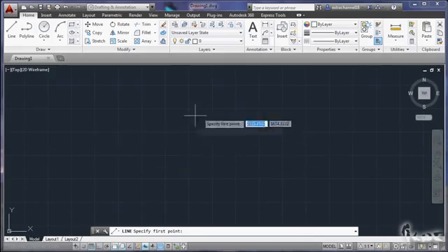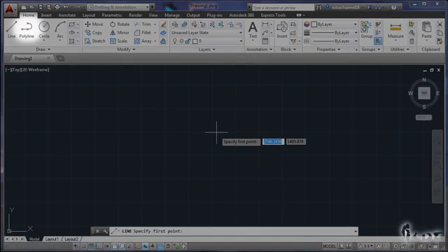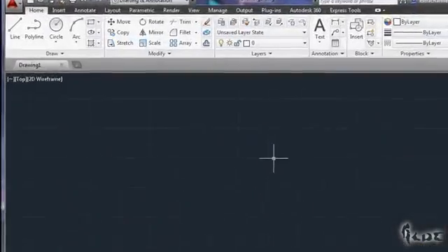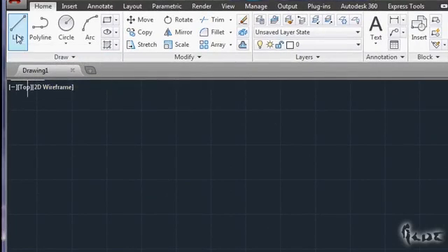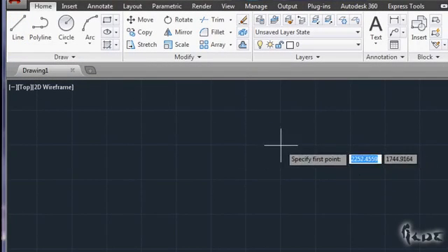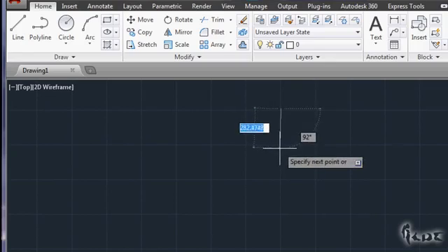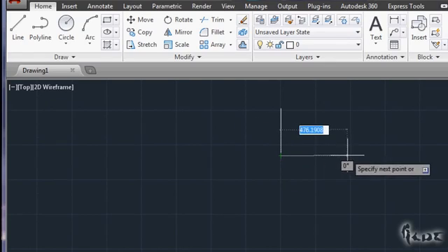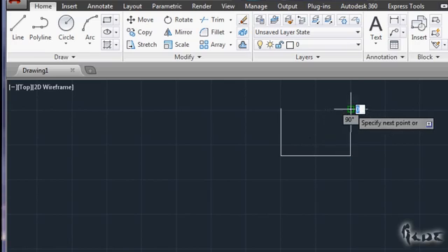Very important in 2D drawings is the polyline. This is pretty different from the line, since it puts together lines and arcs. Let's see it better. When you draw lines to create a polygon, they stay defined separately, so that when you click on one of them, the selection acts just on one line and not on the whole polygon.